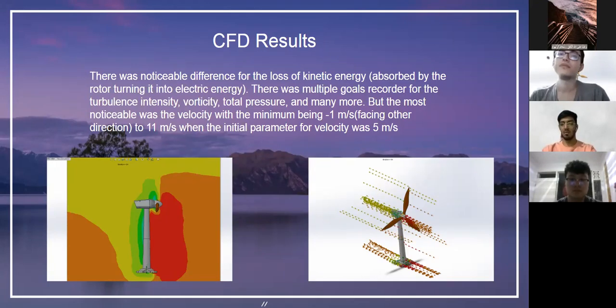However, in practice, when blade losses are considered, a 3% loss is incurred for a two-bladed design, and a 7% to 13% loss for a one-bladed design, when compared to something like a three-bladed design. But someone might ask, why don't we do a four-bladed design? It in fact offers marginal efficiency. It increases, but it does not justify the manufacturing cost of an extra blade.